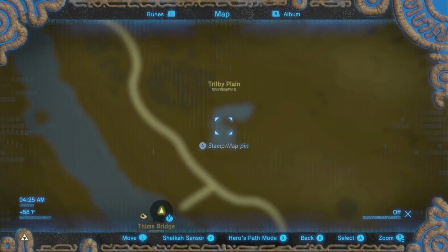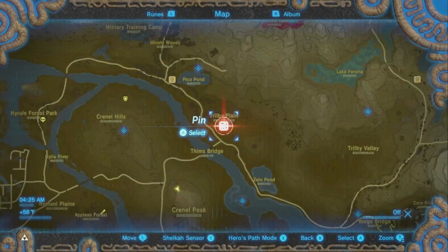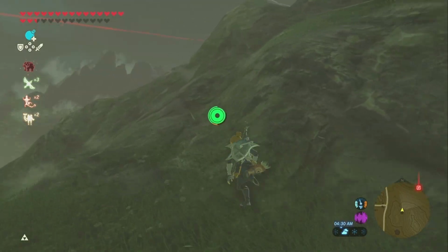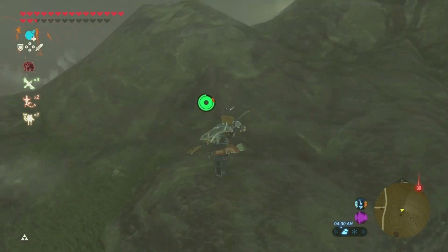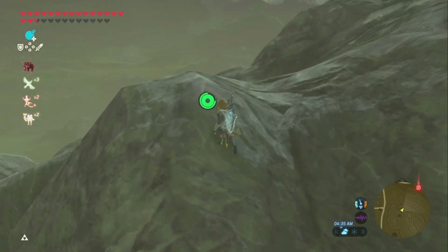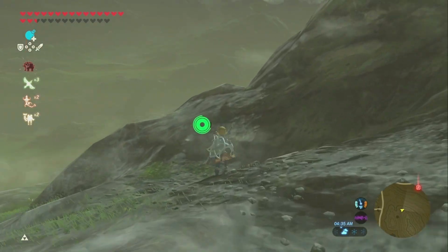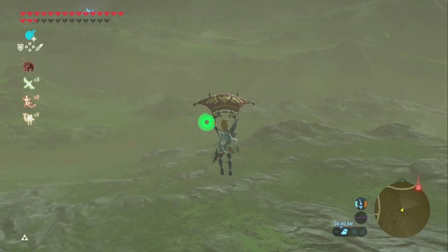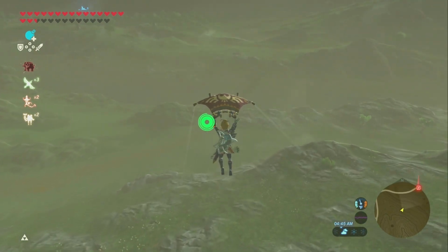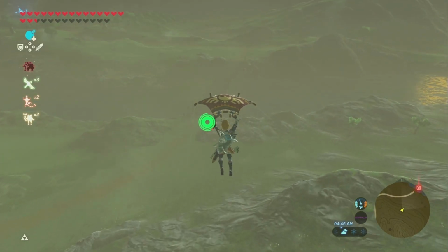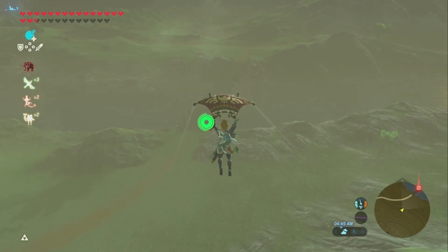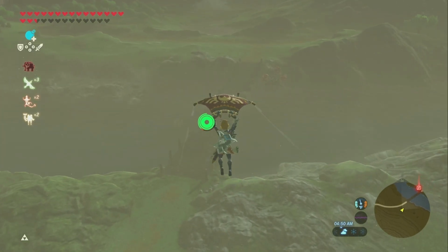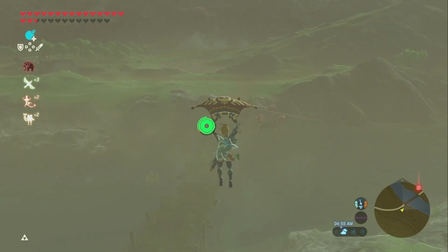Garages. We don't want gas or oil-fired water heaters in garages that are less than 18 inches above the floor. Actually, it's the burner and/or pilot that has to be at least 18 inches above the floor. We don't want gasoline vapors to be ignited by a pilot or burner on the water heater. Mechanical protection from vehicles should also be provided for water heaters in garages. Concrete-filled steel pipes set into the floor are one common way to accomplish this.